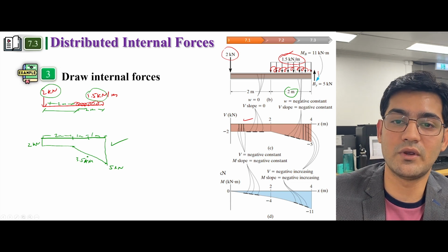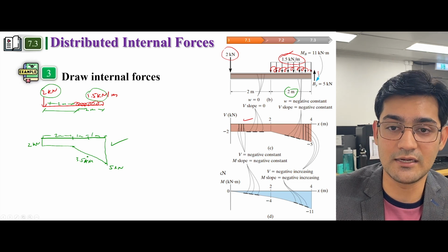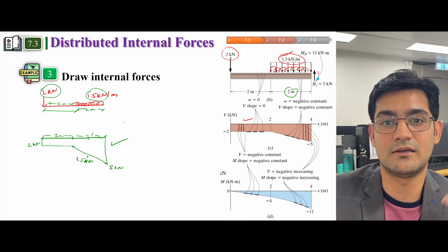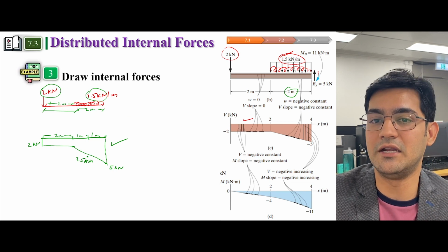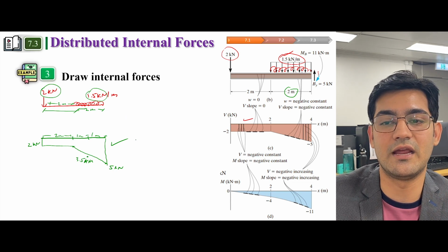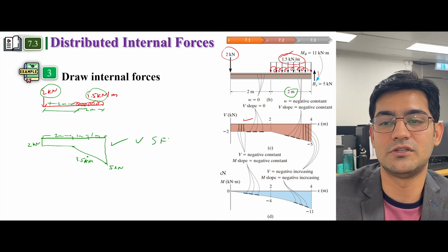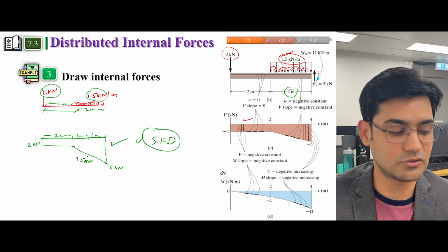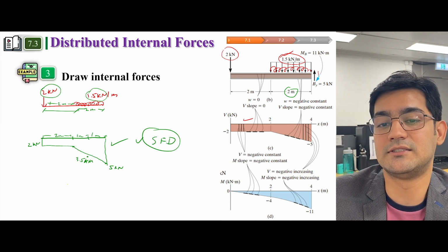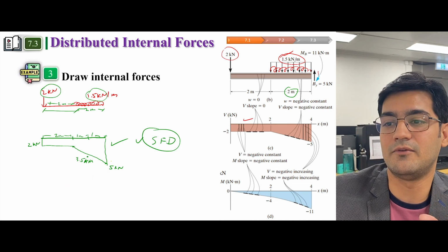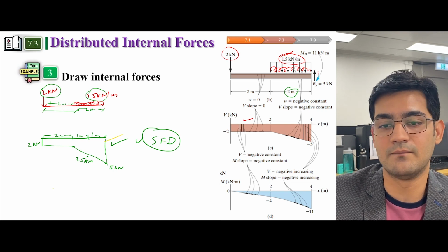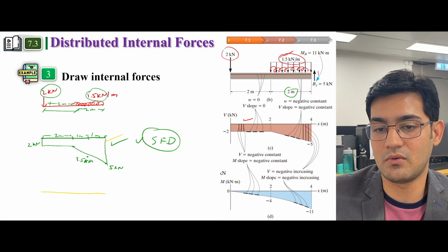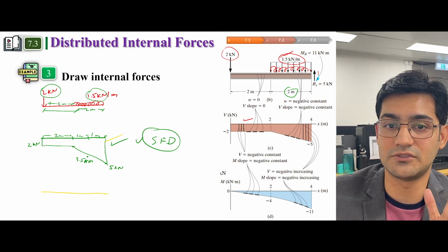So before, the equations we were trying to formulate resulted in these relationships. If you have a loading condition, you just keep on taking the integral of those loading conditions and you can get the shear force diagram. You can also draw the bending moment diagram in a similar way, but the bending moment diagram can be formulated by taking an integral of the shear force diagram. So we have a shear force diagram now, and we're going to take the integral of the shear force diagram